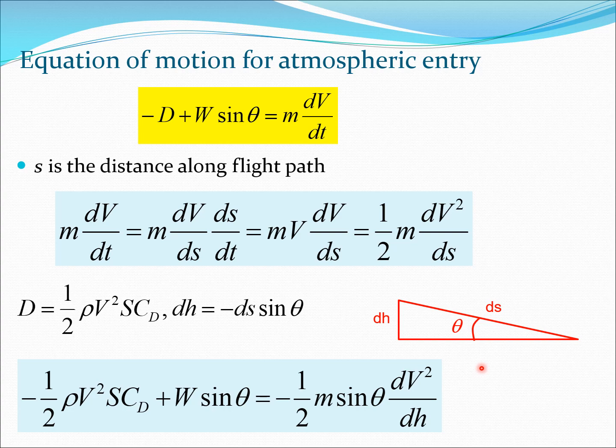So it's measured with respect to the horizontal line that's positive in that direction. So that's why the change in sign happens here. Now the basic definition of drag is D = ½ ρ V² S C_D, C_D being the drag coefficient, S being the area we are using here for the reference. And then we can write this equation out.